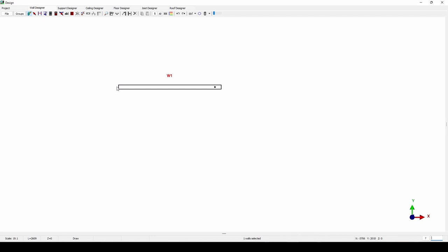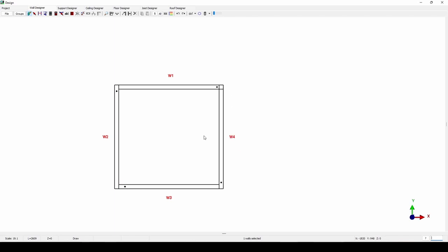Now starting with your next wall, we'll click close to the end of our existing wall, just like that. Same thing going all the way around there. Click, click, and click, click for the last option right there. Notice that corner is not sitting correctly, so we'll be using the selection tool to make sure that those snaps are done perfectly.